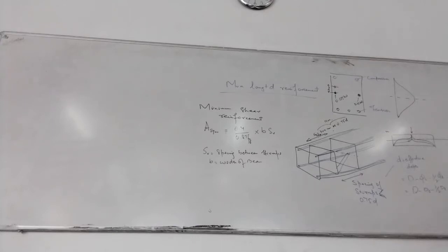If you go directly first to clause 40.3, minimum shear reinforcement, which we just discussed. Where tau v is less than tau c, given in Table 19, minimum shear reinforcement shall be provided in accordance with 26.5.1.6, which we just read. Table 19 is given on the next page.